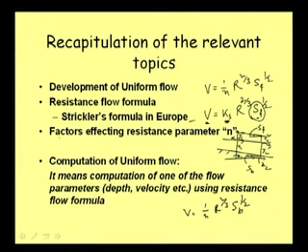Well, then of course, we did discuss the factors affecting resistance parameters. The resistance parameter N is affected by many factors, and that part we also discussed in our last class. Although for a particular channel we may specify some definite value of Manning's N or maybe Chezy's C, in reality this sort of constant value is not possible, say with the change of depth.